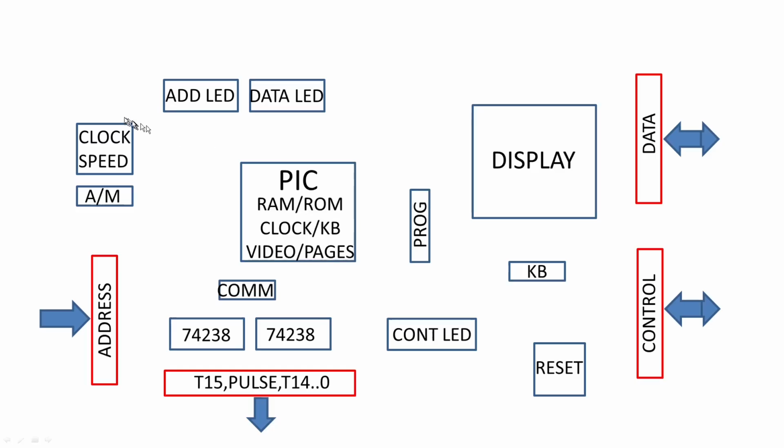On the left there'll be a potentiometer for setting the clock speed, so you can speed things up and slow them down. There's also an auto manual switch, so you can switch the whole system to stepped control, where you can step it through a quarter of a clock cycle at a time. We'll go through that in more detail when we look at the software that's in the microcontroller in another episode. And then we've got a comms port on there, which at the moment isn't used for anything, but could be. I just put it there because the facilities were available.